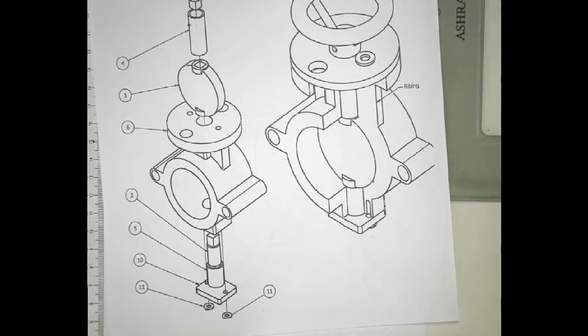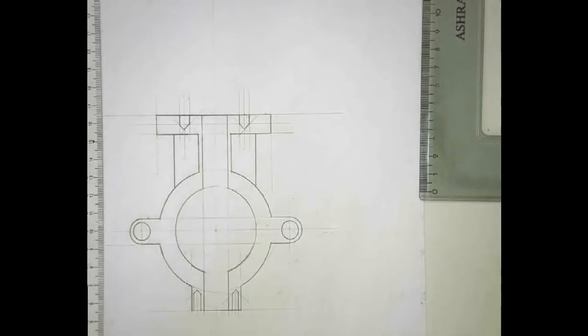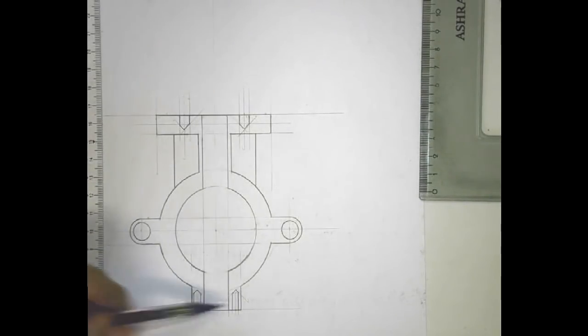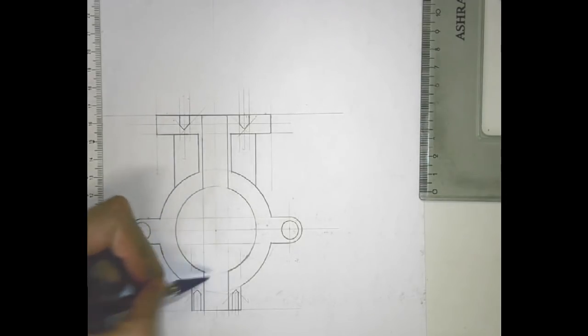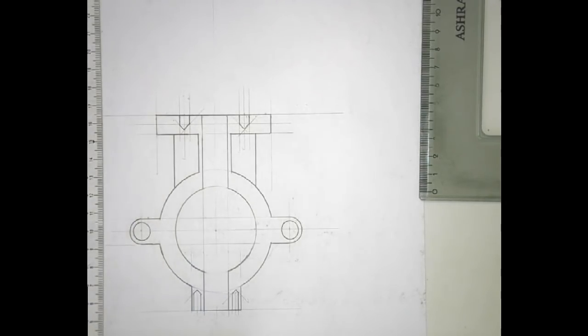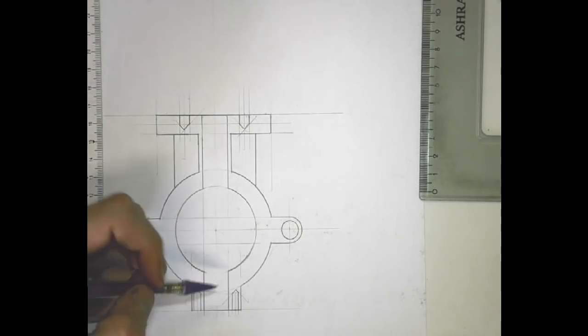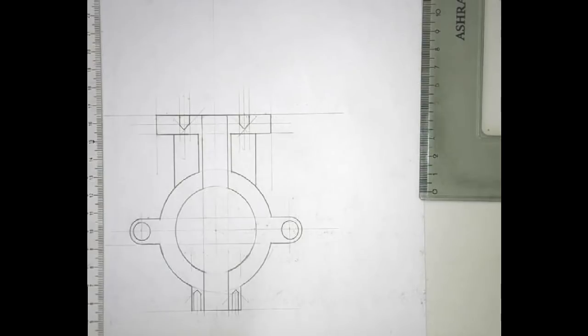Now that we have the housing completed, we're going to look at building the rest of the components around the housing. So again, we'll start with the components at the bottom. We're going to look at the bottom plate, which is the cover plate. We'll look at the cover plate, the bushing and the shaft at the bottom. The cover plate will just fit directly onto the bottom here, the bushing will fit into here, and our shaft will fit into the bushing and protrude over there.